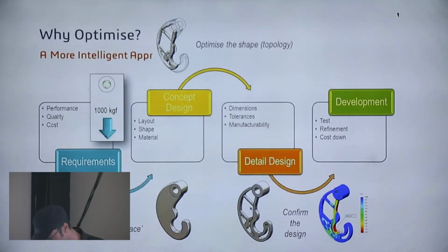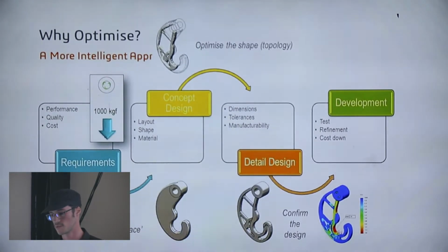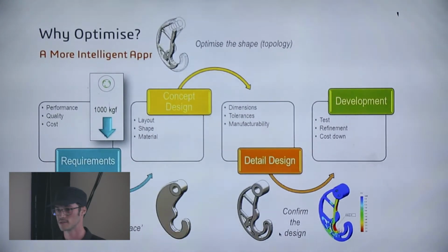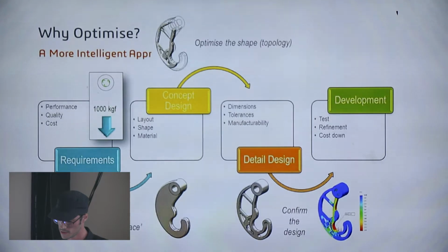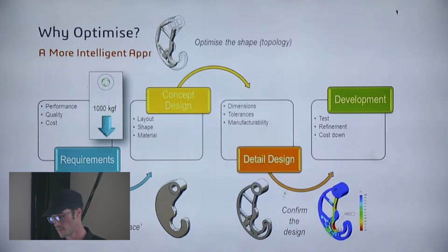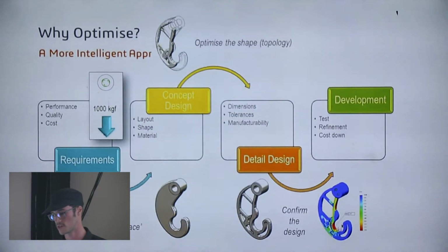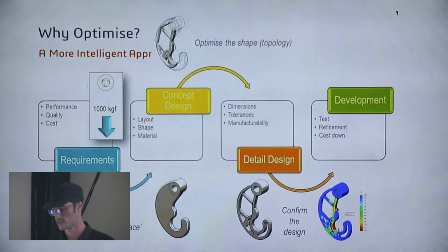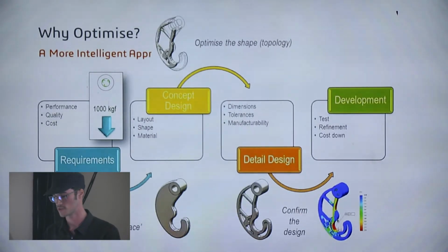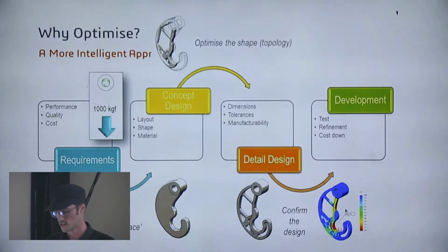Dimensional tolerances. What I probably would have done was made this beam the same height as all of this plane, so you could have just water jet or plasma cut it out of a flat piece of stock. But knowing to have a beam here and a beam here and a beam here, I never would have guessed that. And the programs that make these objects generally also test the objects. So you put your cleaned up shape optimized part into the simulation. It tells you this beam's thin here and this beam's too thick. Red is where the forces are, and this comes back later. You have this kind of loop where you shape optimize, clean up, and then you rerun the experiment again.